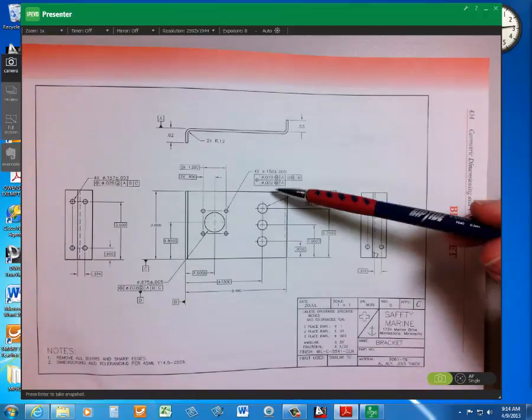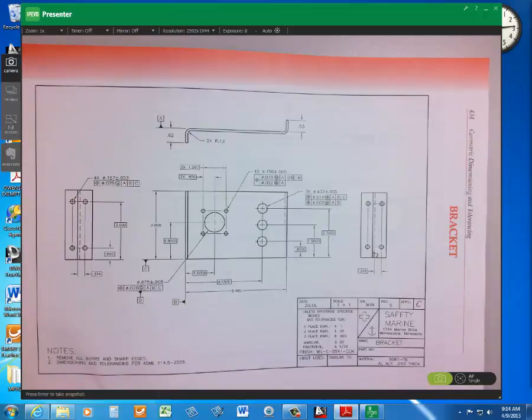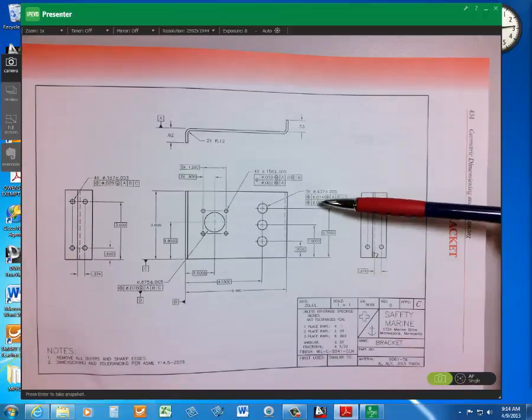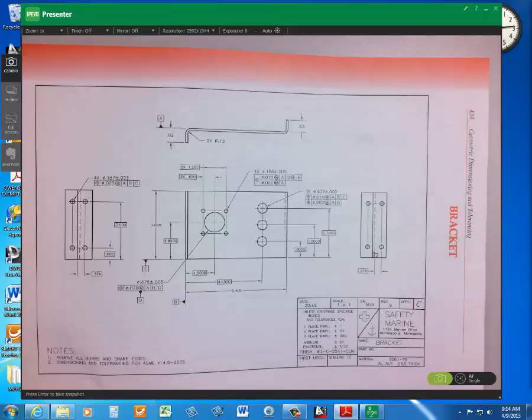So we got 3 holes. And this one is kind of a funny word, two single segment feature control frame. The upper part of the feature control frame specifies your pattern of 14 thousandths MMC, where the pattern features lie in a group relative to A, B, and C. No modifier, so that means regardless of feature size.